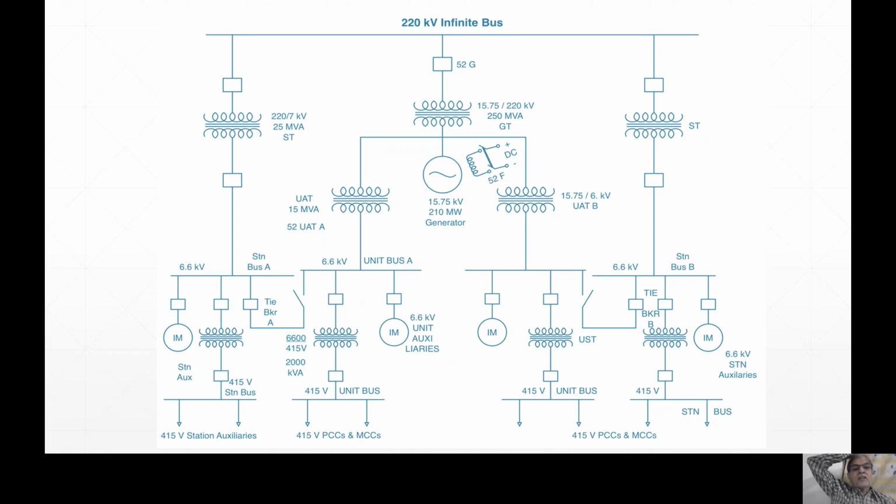One state can get power of some 100 megawatt or 200 megawatt. That was the MOU. But the other states started fetching more power. So that was the reason why the cascaded tripping initiated. And then it was followed by pole slipping of generators and many more things.